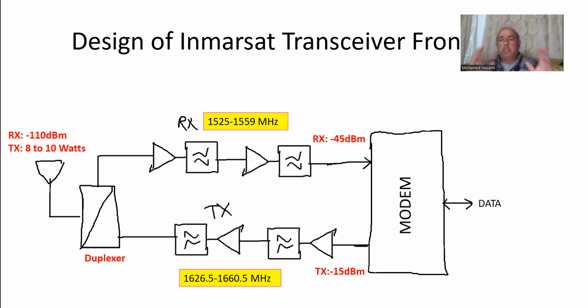We do this, we system simulate it using SystemVue Pathwave baseband and RF system simulator. We verify it. And then after that, we go ahead and start going into more details, up to the point where you get all the schematics ready and start doing layout. And once you do the layout, then you come back to the RF designer and try to do what is called post layout verification from an RF, EMI, and signal integrity point of view.